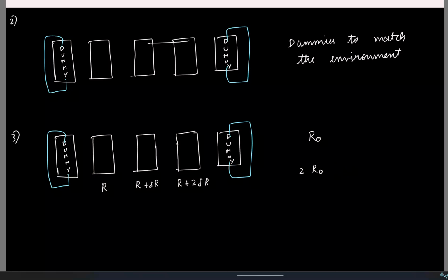And we see that if I connect these two and call this my 2R0, that is not working. So can you think of something by which I can get it? Basically I have 3 instances. I'll have to connect 2 of them in series so that the effective series resistance is twice the other resistance. Sir, I don't know, but there will be a resistor to the left of R also. That will be R minus delta. No, that doesn't matter, right? We are only interested in 3. Means assume there will be something R minus delta, then put them in series.